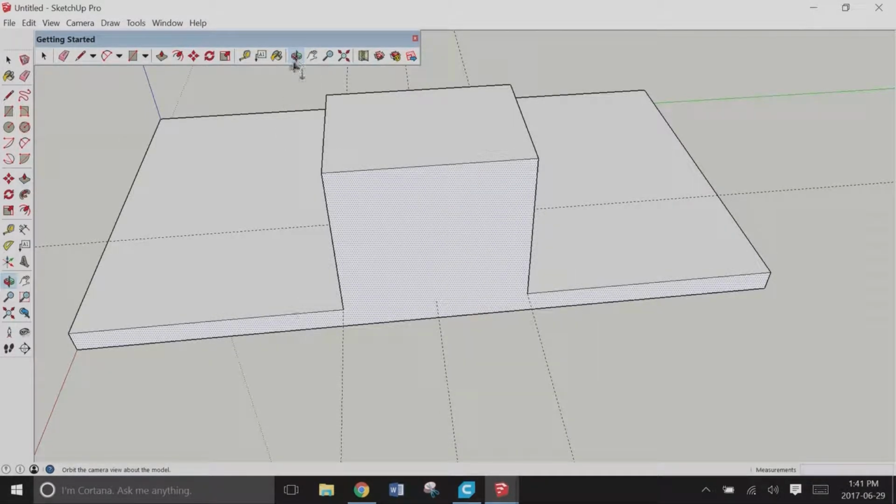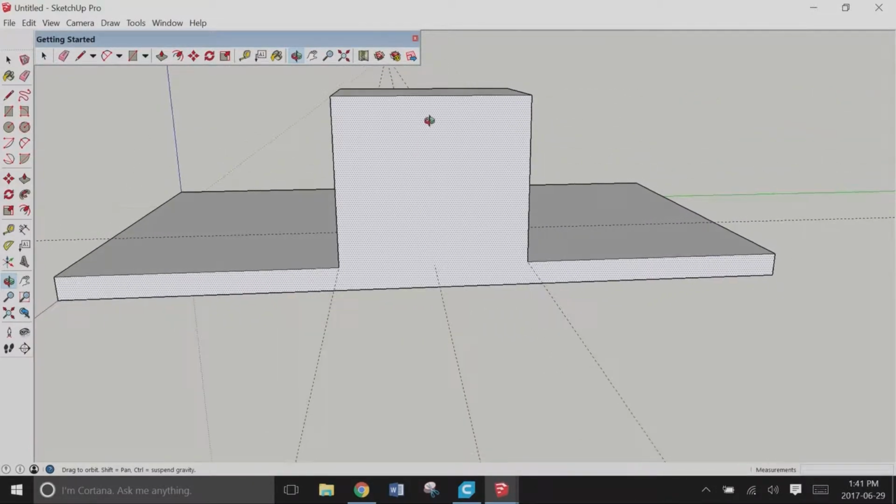So now rotate again. Now this is the front. So now to adjust for our 5mm thickness, I'm going to go in 5mm on my sides. One of the things about SketchUp is it will snap into place if it's a measurement you previously used. So I just use 5mm. These here now will snap in to my 5mm. For the bottom, I'm going to go from corner to corner. So now this is what I'm going to need to remove.